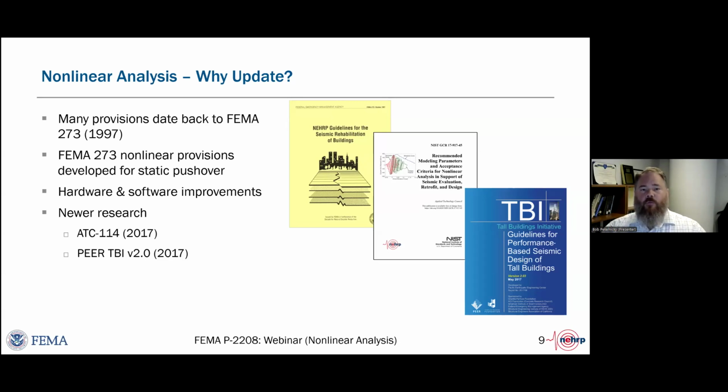The other great work was done with the Tall Buildings Initiative for guidelines to performance-based seismic design of tall buildings. Starting about 20 years ago, engineers started doing nonlinear response history analyses to design tall buildings, recognizing the benefits in being able to do structural systems that were slightly not in conformance with ASCE 7, but could produce the same reliability of resisting collapse in a maximum considered earthquake.